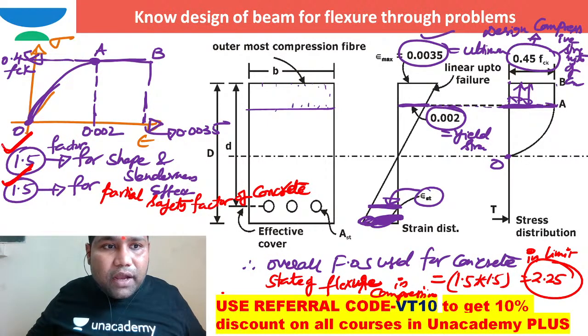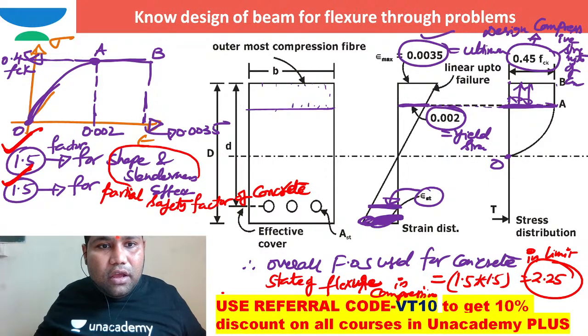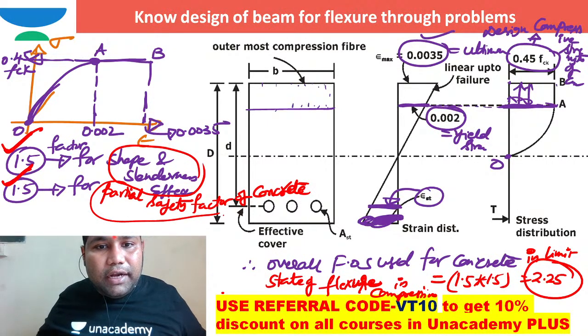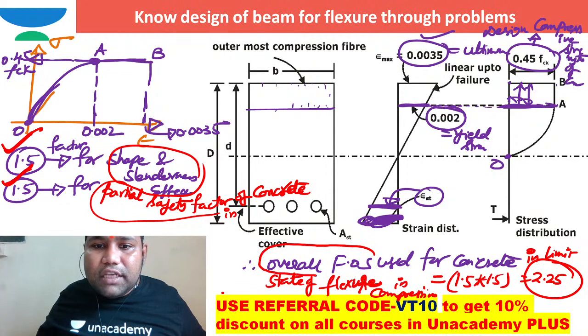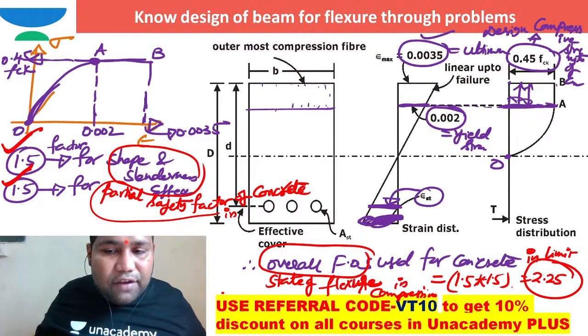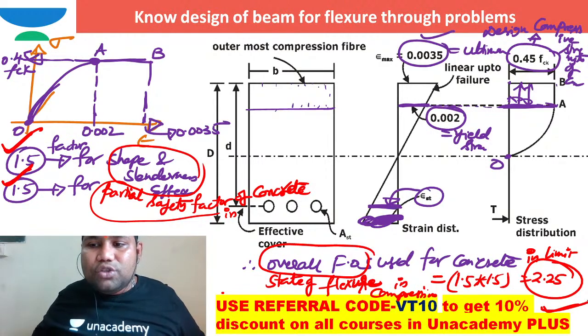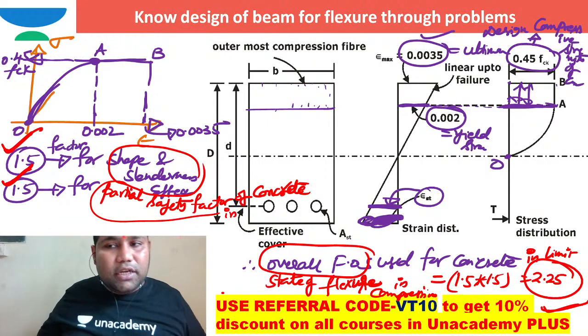1.5 is the factor of safety for shape and size effect. Another 1.5 is the partial safety factor for concrete in limit state of compression. If I want to work out the overall factor of safety, it is 1.5 into 1.5. Just 1.5 is not correct. Finally the answer is 2.25. Is it okay, dear Shebin Sailuddin, where you are making a mistake, right?